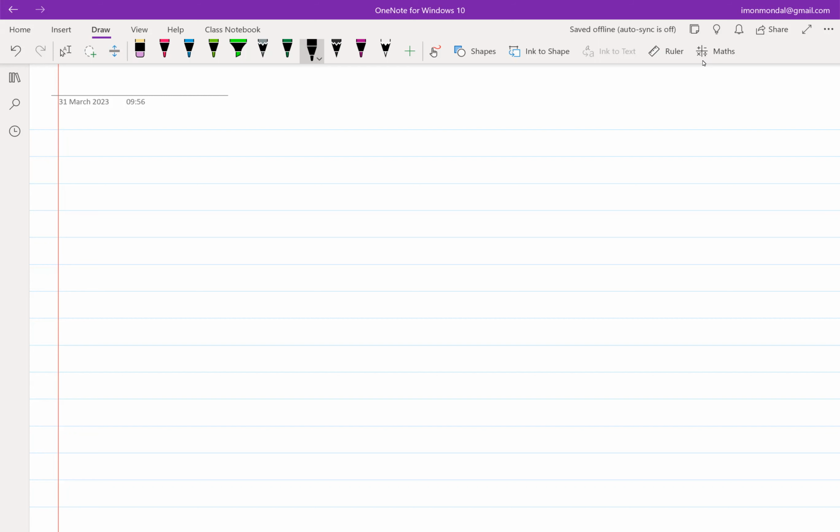Now, one of the problems of a good amplifier, the only amplifier that we have studied in this course till now, is the common source amplifier. In a common source amplifier, our gain is minus GM times RL. Now, GM times R. The expression of GM you can write in any format, but let's say I write it in this format.